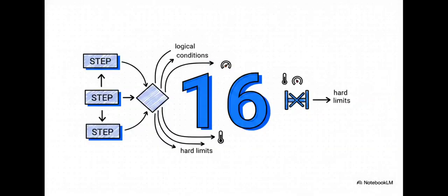Once a step finishes up, it hits a transition. Transitions act as the feedback gate to actually advance the sequence forward. But, just like the steps, they have hard limits too. They're strictly capped at 16 logical conditions. This keeps your logic tight, predictable, and honestly, incredibly easy to troubleshoot when a sequence inevitably gets stuck waiting for a specific temperature or pressure to hit.